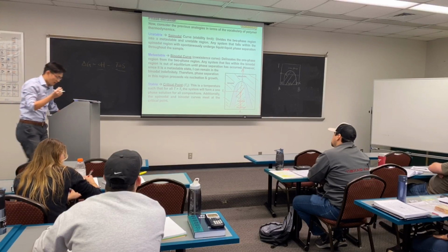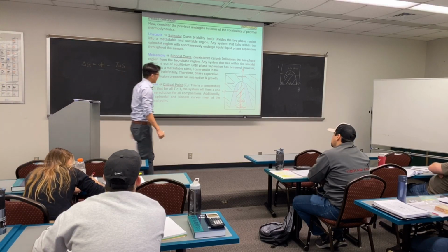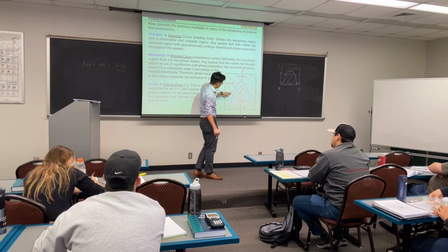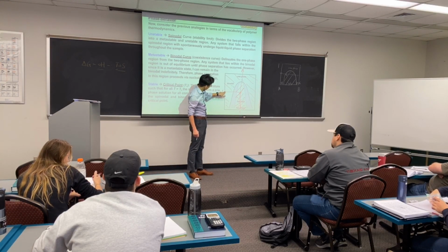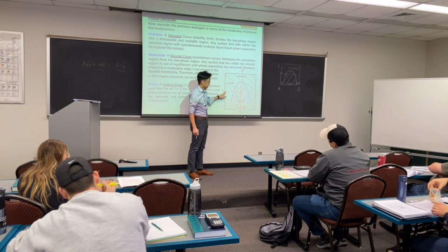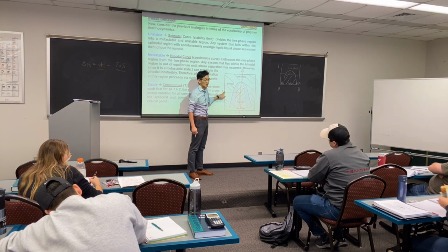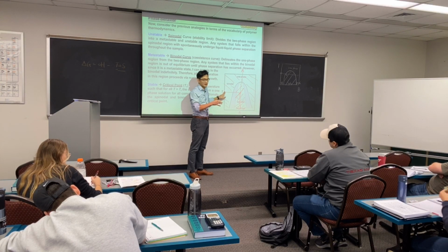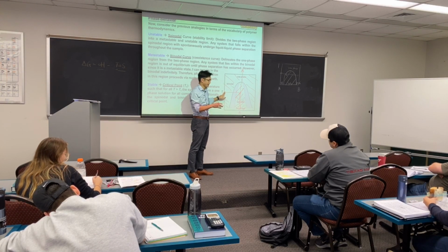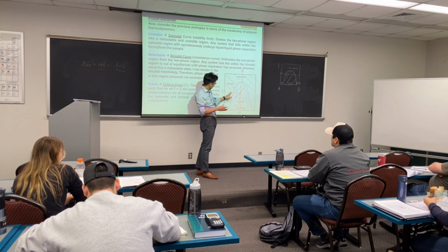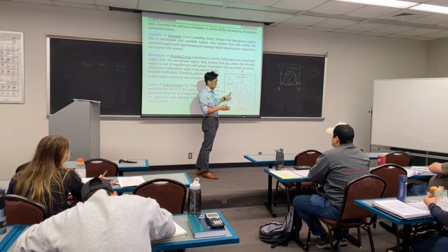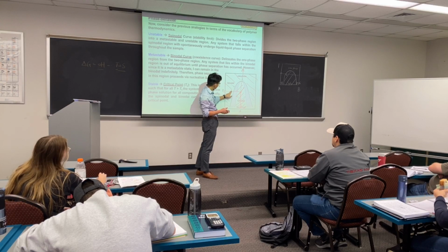So we can read the phase diagram in two ways. First is going horizontally. This data point, let's say here, means I have 99% of A molecules and 1% of B molecules, they will mix. If I keep going, 75-25, still going to mix. This is still in one phase.